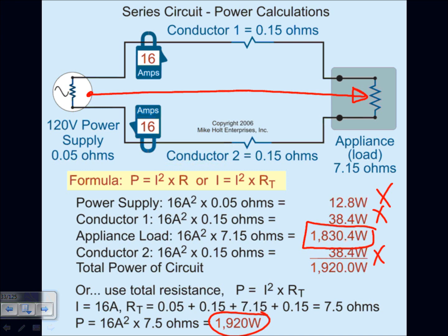If you generate 100% power here, you should consume up to probably 90% of it right in here. Otherwise, you can't stay in business. How do you do that? By minimizing the losses in the conductor, using a bigger conductor, and by making your equipment that generates more efficient, with less losses in the equipment. Does that make sense? And I know everybody knows how to calculate the power. You take the voltage multiplied by the current, or the current squared multiplied by the resistance, or the voltage squared divided by the resistance. I'm not going to go through the mathematics. You guys should be very familiar with it. I'm going to talk about the concept.